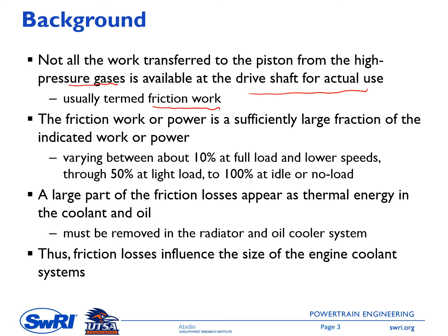And the friction work or the friction power is a sufficiently large fraction of the indicated work or power. It can be from 10% at full load and lower engine speed, and then through 50% at light load, and it will be 100% at idle or no load. So at the idle, the engine doesn't output any power.